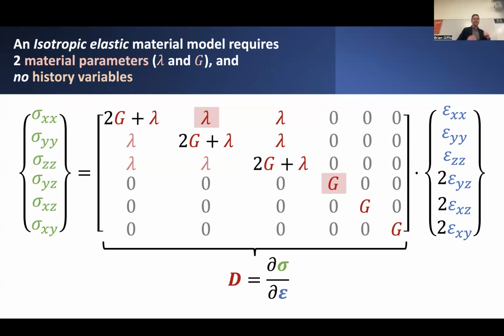So anytime that you're using a material model that invokes certain assumptions or limiting behaviors, you do have to exercise caution and judgment, because ultimately it's up to you to decide: are these models really operating within their intended ranges of behaviors? And if they're not, that's something that you have to assess. You can go back and check, in my analysis, did the stress ever exceed some kind of theoretical or experimental threshold? That's something that you have to verify. So just bear that in mind.